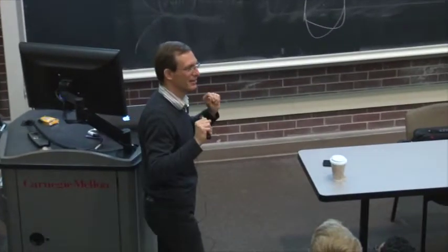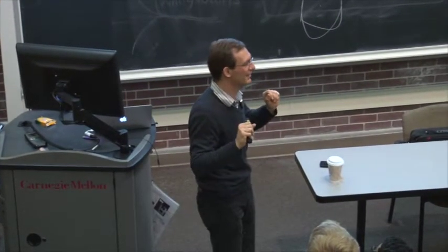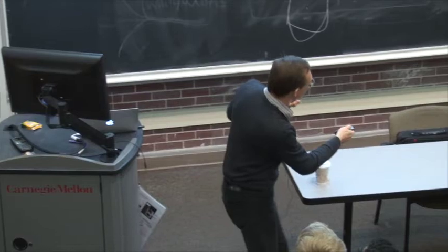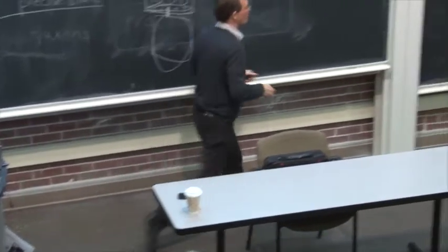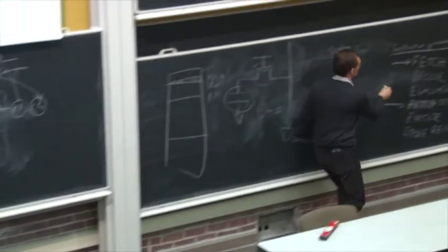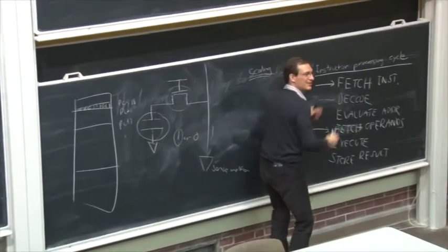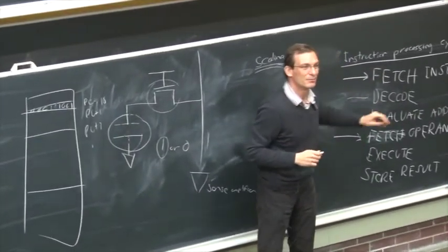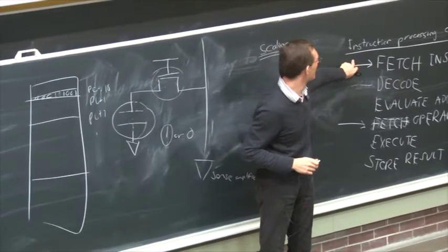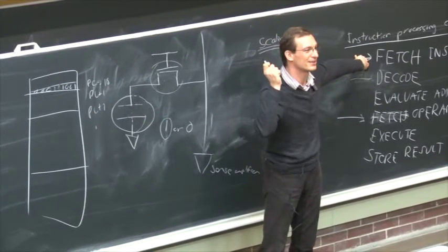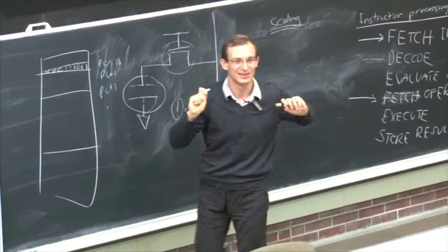But today we use techniques like pipelining. Are you guys familiar with pipelining? Basically, think of this as once the previous instruction moves to the decode stage, you can actually fetch the next instruction, right? You can fill the pipeline this way. But if you think about it, that violates the von Neumann model, right? You should not be fetching another instruction.